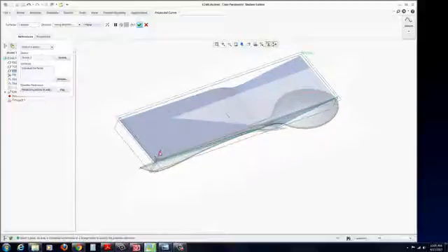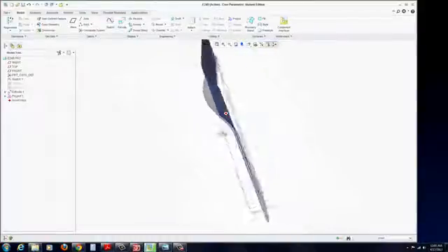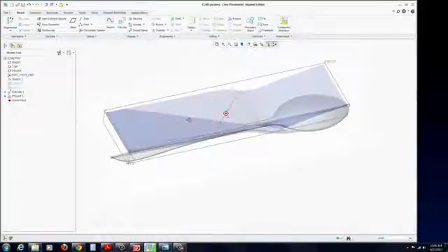Now what you'll see is a little arrow, and it looks like it's projecting our sketch on there. That's fine. But just to be on the safe side, I've seen strange things happen when you have it in reverse direction. I want to project it down onto the surface. And hit the green check mark. Now we have a 3D guide curve for the outer edge of the spoon.